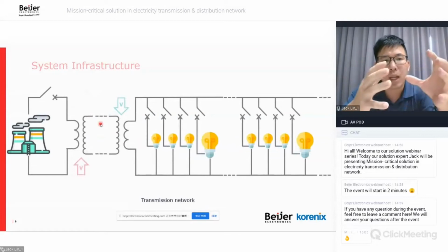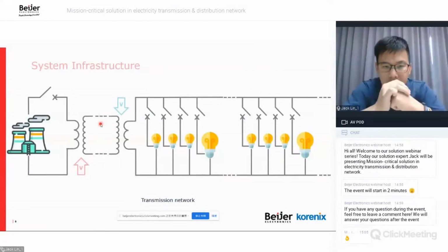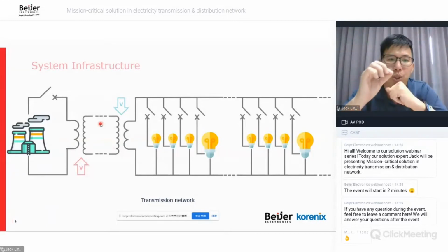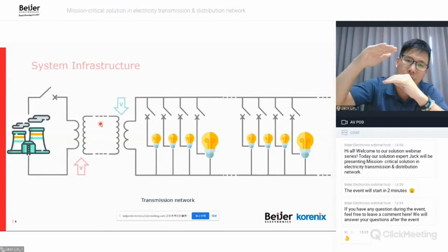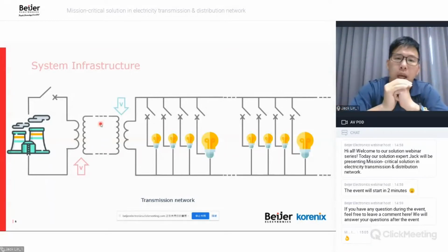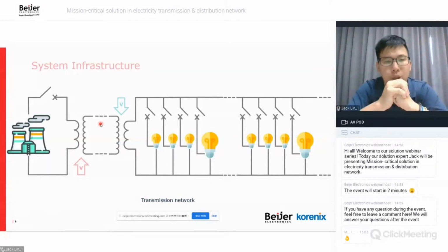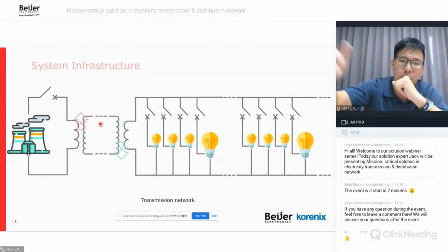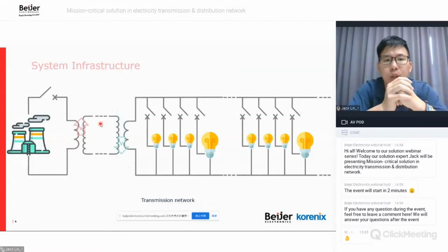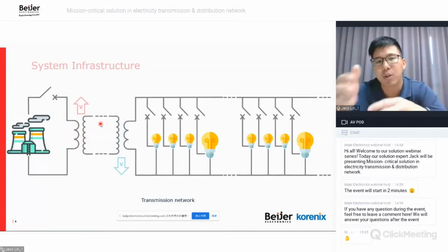The battery becomes a power plant to generate enough power for the millions of consumers that require electricity in their houses, in their factories, okay? You have a power plant to generate the power. And then because of the long travel distance, the power loses over the distance, okay? The current, the power decreases throughout the transmission in the network. And therefore, the solution is to step up, to increase the voltage of the electricity before it travels the long distance, and then decrease it when it gets to the local side, the consumer side, to adopt the voltage acceptable range of the local device, in our houses or in the factories.